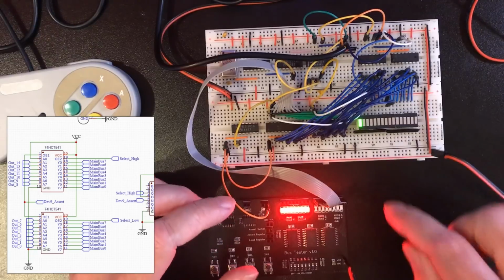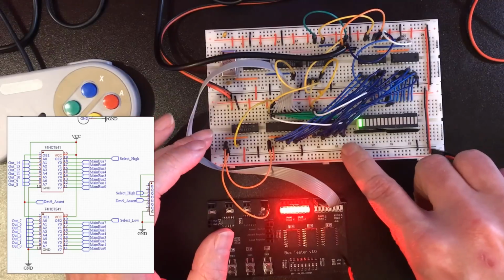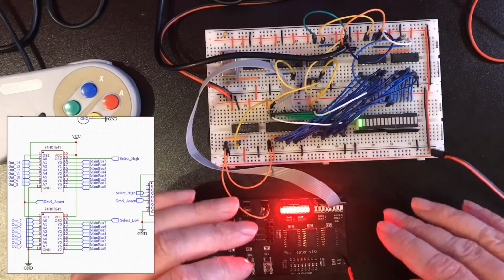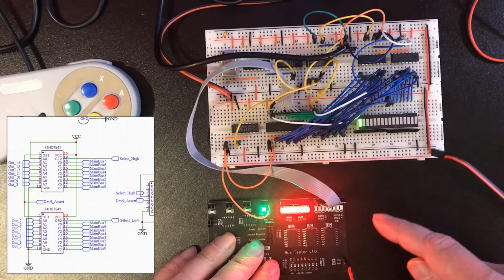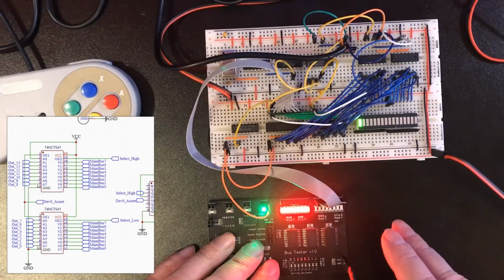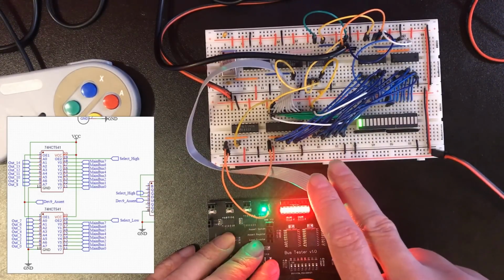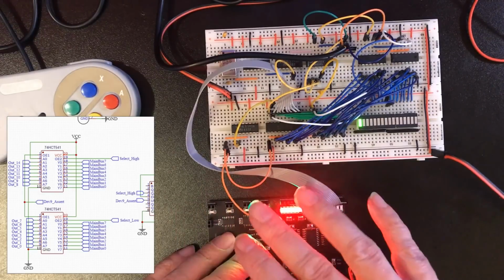Now, in other circuits, instead of a line driver, I've used a D-type latch as the output, and I've signaled the latch to load when the load line goes low, and then I just kind of keep it so it samples the data. But we don't have that here. In fact, if we swap these out for latches, we wouldn't have the second enable line, and then we'd need the demultiplexer, and we've added an extra chip.